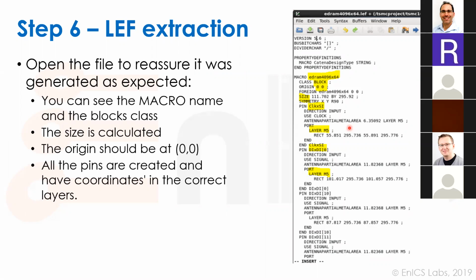So that's something that we can do, or you can just change the routing a bit by going up or down a metal layer to change this ratio. It's really easy to find out. The problem is that when we make a LEF file, we don't see the gates even. We don't see all the metal layers that are made underneath. The LEF is an abstract. It takes away from the router, so it doesn't have to see everything that's inside. So what we have to do when we provide the LEF is tell it what the numbers that are relevant for calculating this ratio are. Okay, so that's why we have antenna information inside the LEF.